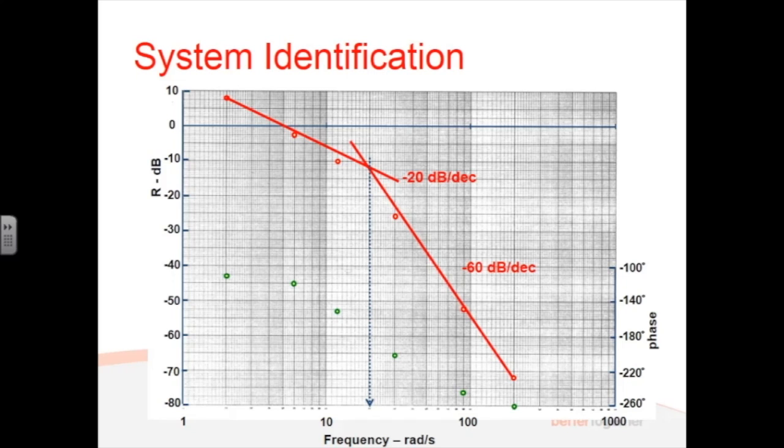Close. It's going down. Is that not a lag? So it's in the bottom. It's a lag. Okay. So we've got an integrator and a second order lag. I forgot to ask you about the gain. Is this an integrator by itself, or is there a gain involved?